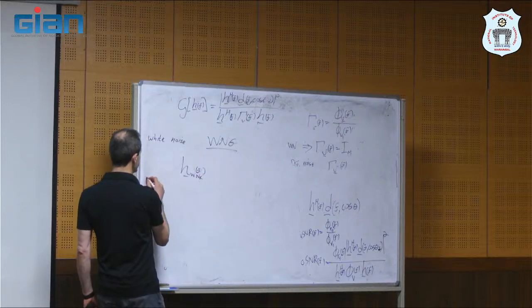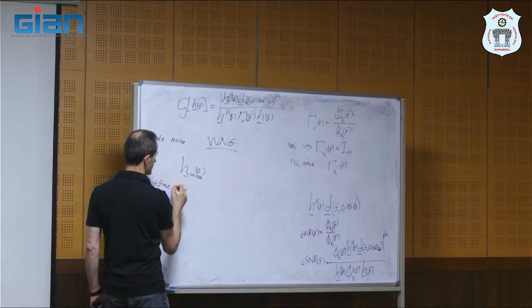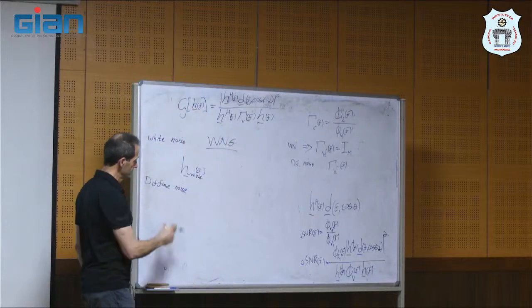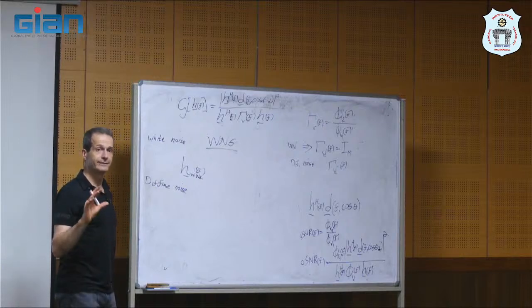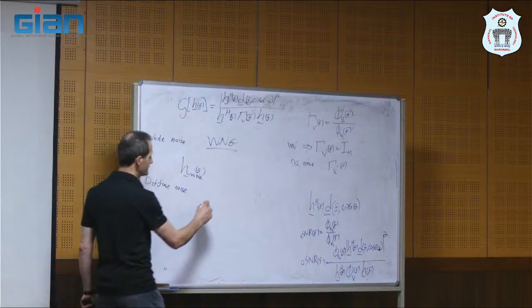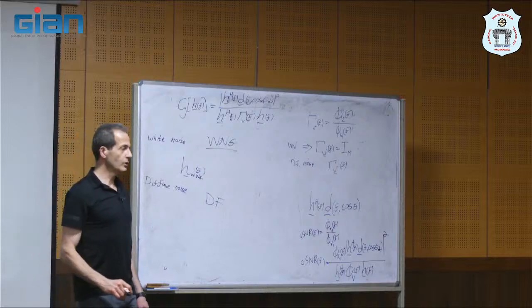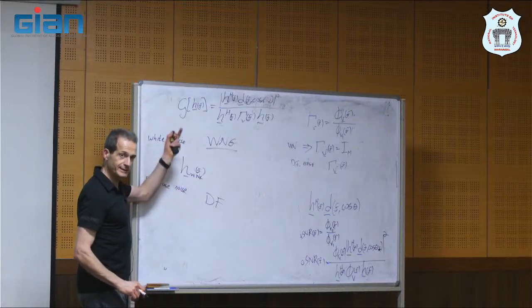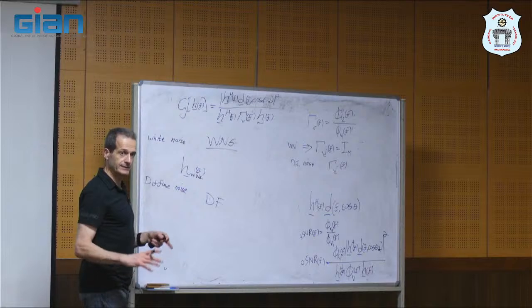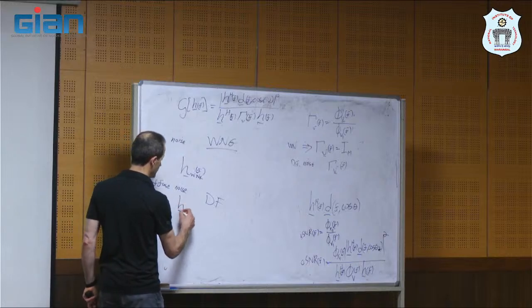If the noise is diffuse noise, then the gain in SNR, under the assumption that the noise is diffuse, is called directivity factor. So we call it directivity factor. A beamformer that maximizes the output SNR, assuming that the noise is diffuse, is called beamformer DF or max DF.